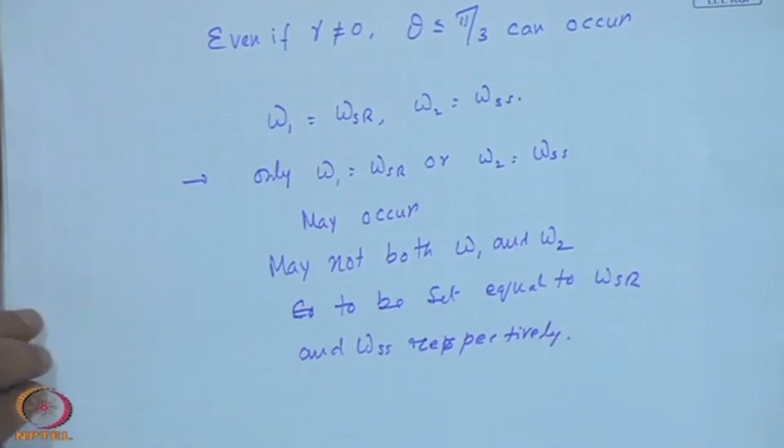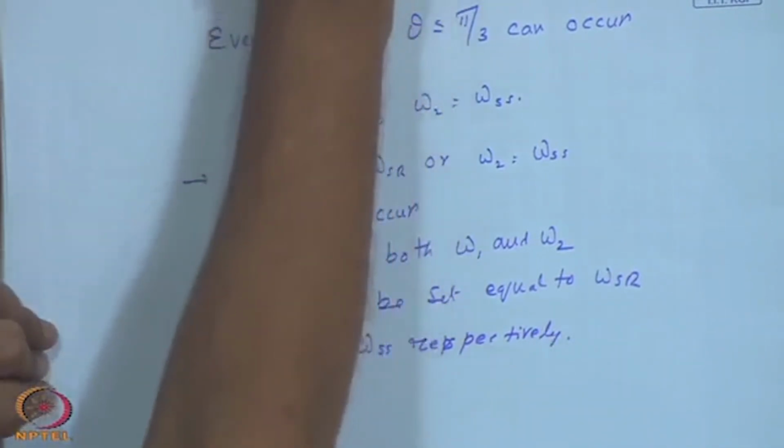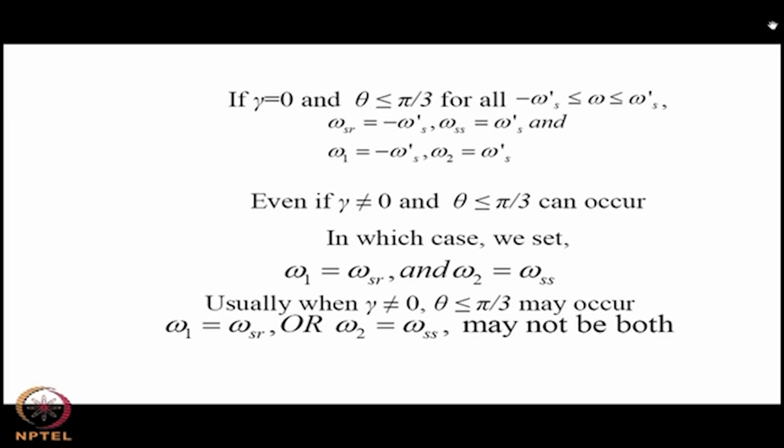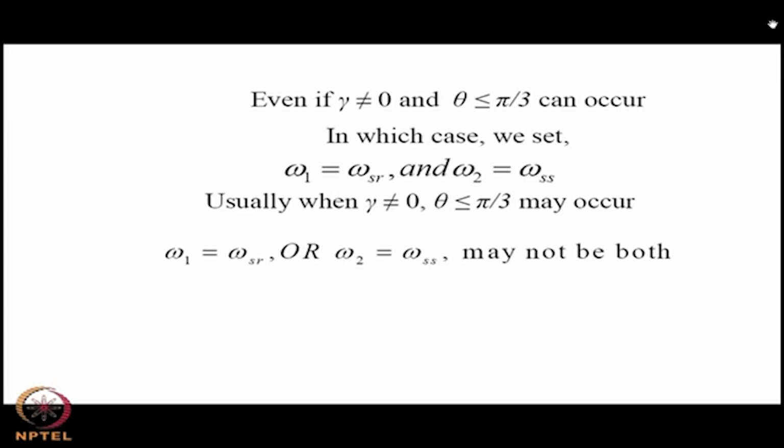So, let me repeat, this piecewise integration has become necessary because of the description for tau alpha by tau alpha normal being set in two intervals for the angle of incidence theta. And if you consider a simple south facing surface in the negative declination case, we know that the collector starts with an angle less than pi by 2, which may be greater than 60.